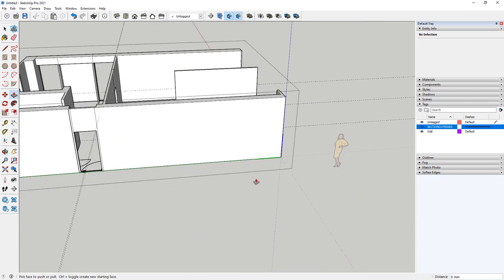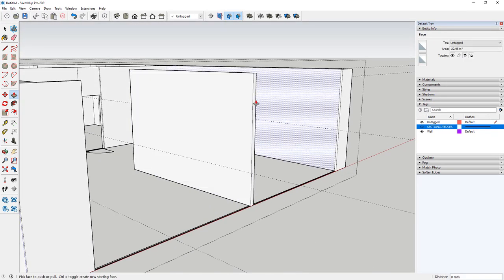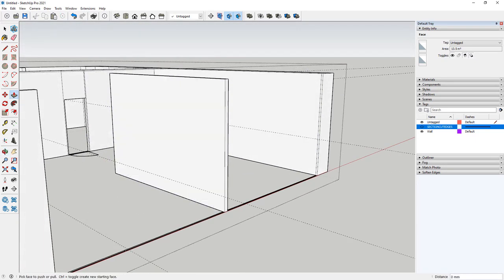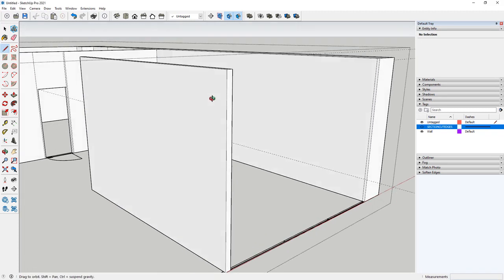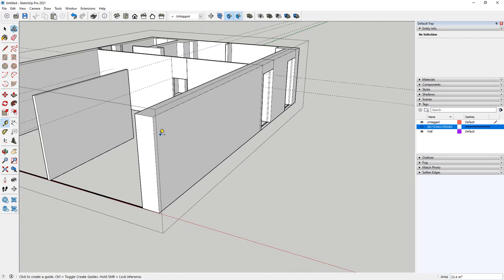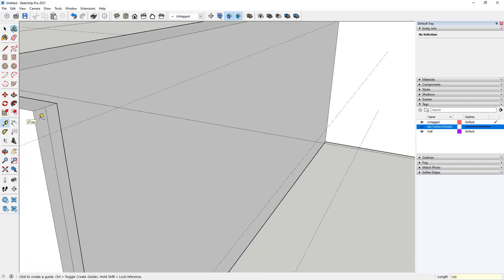And then we have two huge windows in the living room. So we need to also create with the reference line the upper wall. So we'll start from the middle one, but maybe this time also with the reference line. And I guess that it will probably be easier to put it here on those walls. So we put 100 millimeters from the top.